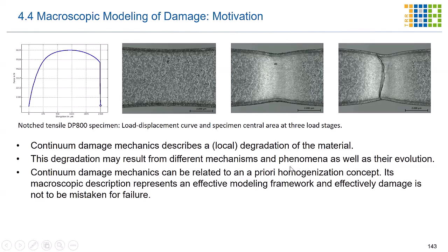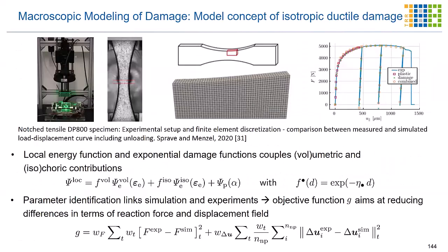For example, we can employ phenomenological models, which describe the behavior of a material based on macroscopic observations, but without considering the underlying mechanism. To model ductile damage in these models, it is common to introduce a scalar-valued damage variable d, or this can also be tensorial. In Lemaitre-type models, often referred to as 1-d models, damage is modeled as the degradation of the elasticity and the plasticity-related quantities.